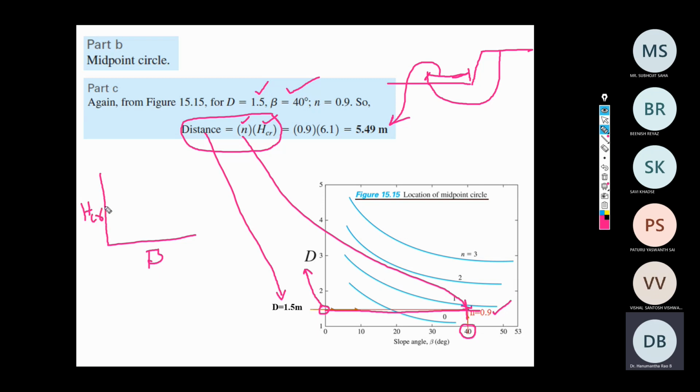With the function as a factor of safety. What is the minimum factor of safety value, corresponding to which you are getting the least factor of safety? So it may so happen that your critical height may increase, then followed by become constant, or may increase or decrease, or it may constantly decrease. Anything could happen. Once you understand this, then you can pick up the critical height based on these trend lines. And other parameters also you can vary depending upon your interest.